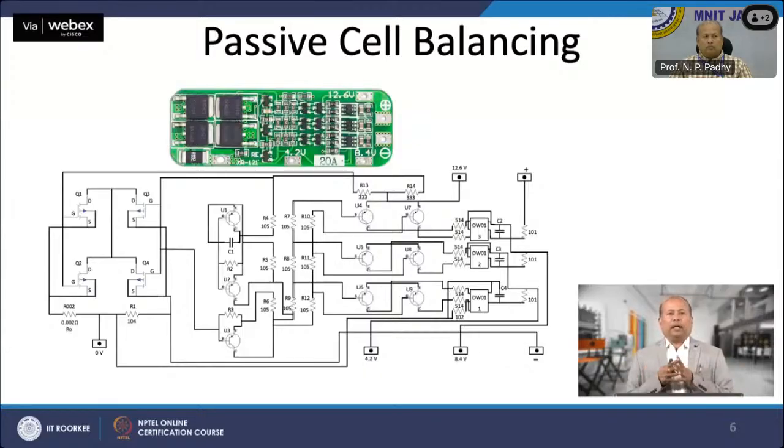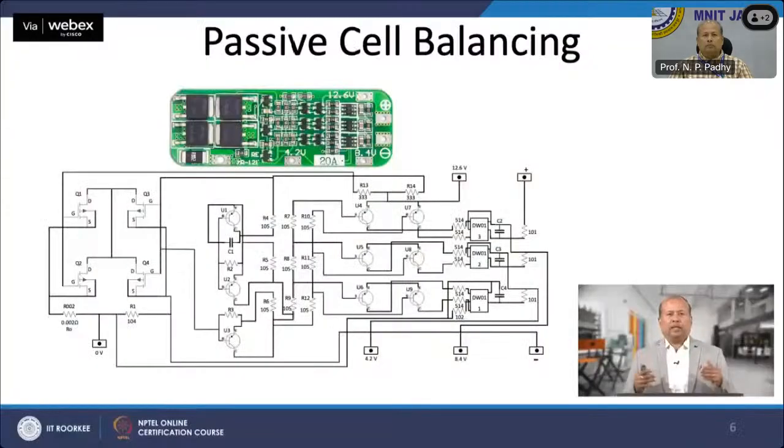After connecting the batteries to the balancer IC, we are going to check the balancing operation for both charging and discharging using the DC power supply and rheostat respectively. Let us observe the charging operation. The battery module is charged by the DC power supply and the path of the charging goes through the DW01 protection IC and through the switching MOSFETs 1 and 2.